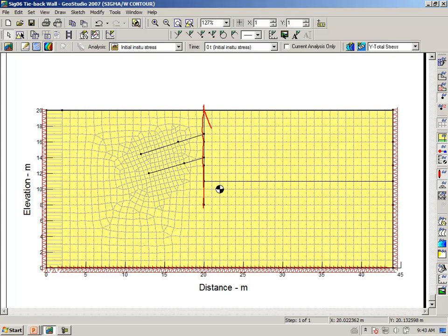What is the stress distribution in the ground here before we come along and take away all of this material here? It is in essence a form of this stress that will have to be retained by the sheet pile wall and the anchor system. So the first thing now we need to do is to make a plot of the lateral horizontal or X stress where the beam, the sheet pile wall, will eventually be.